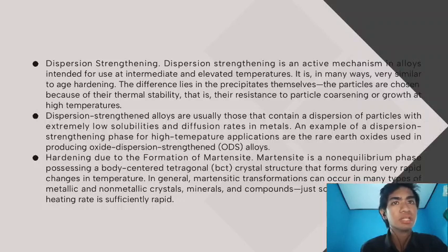Alloys offering exceptionally good thermal stability have been developed using powder metallurgy techniques to incorporate a dispersion of fine Al2O3 particles in a basically copper matrix, which is finished by processing to rod, wire or strip product. This family of alloys, C15750 to C15760, can resist softening up to above 800 degrees Celsius.